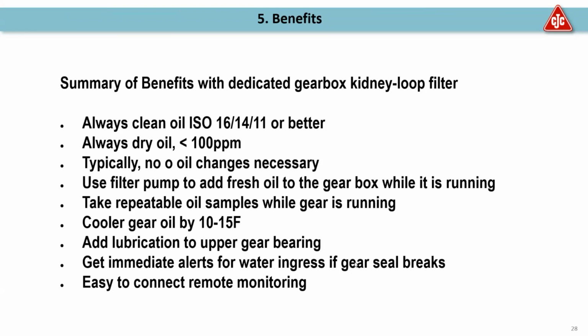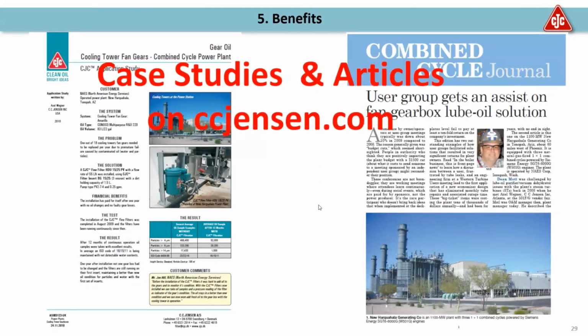What I need to mention in this regard is that if this filter absorbs water, it takes about half a quart of water, and then it blocks. So it'll tell you exactly when saturated and alert you that way that something is wrong in the gearbox. And it is easy to connect for remote monitoring. There are many case studies and articles on our website, so please check that out if you are interested.